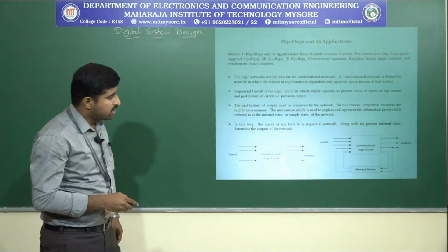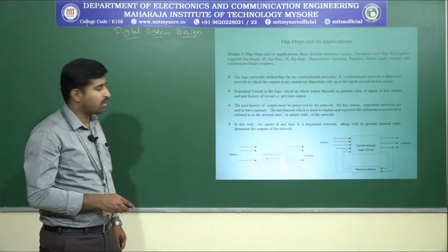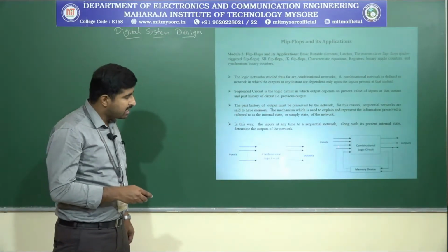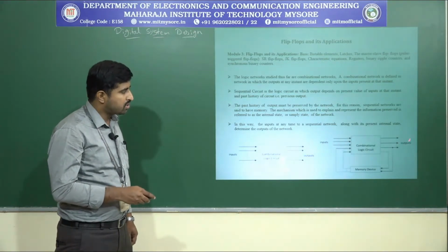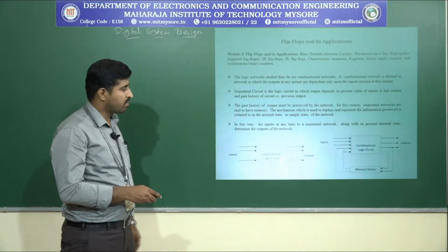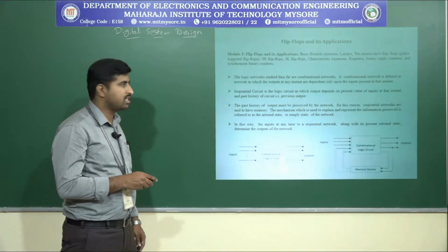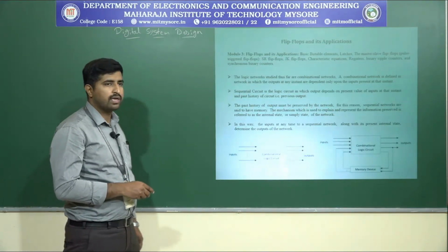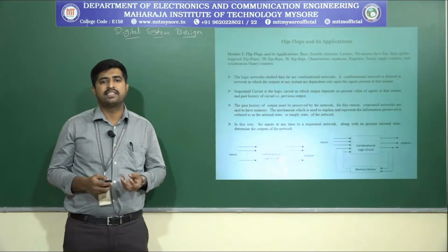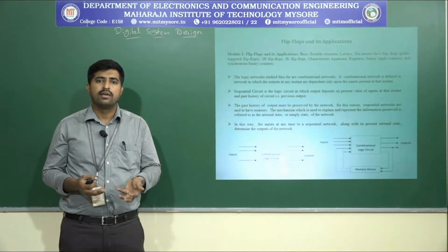Here you can see a combinational logic circuit with a feedback or a memory device. The past output will be fed back as an input along with the current input. According to these two inputs, the present output will depend. That is the sequential circuit. We need to store the previous data, and that's why we need a memory. Whatever data is stored in the memory is represented as a state, that is, the internal state of the circuit or the state of the network.